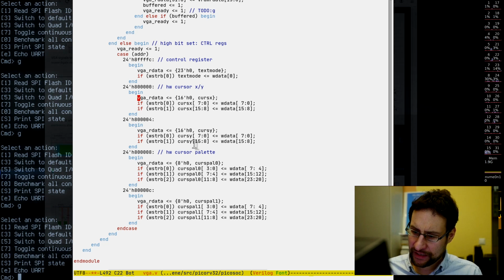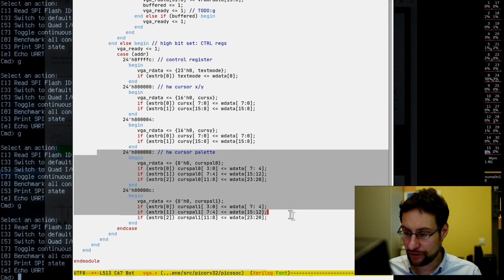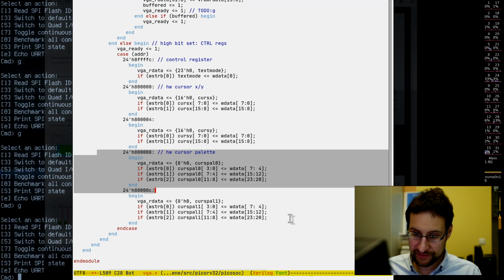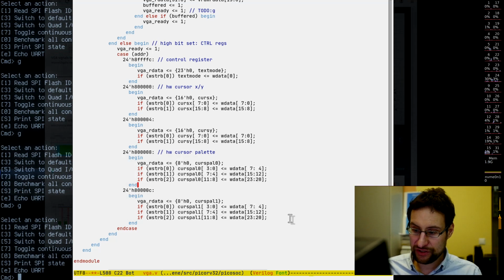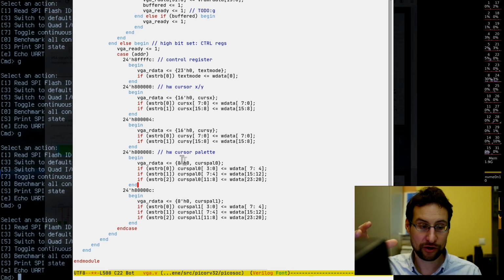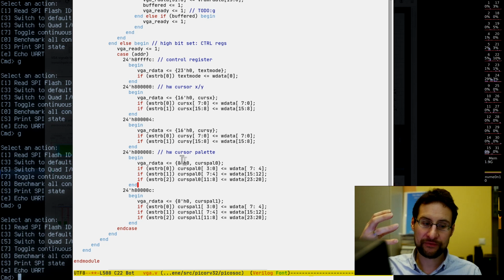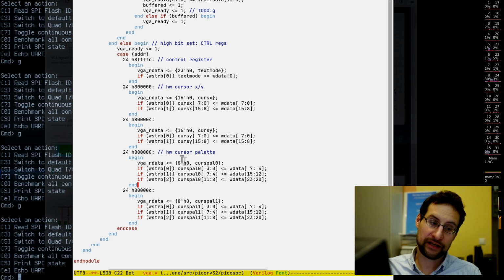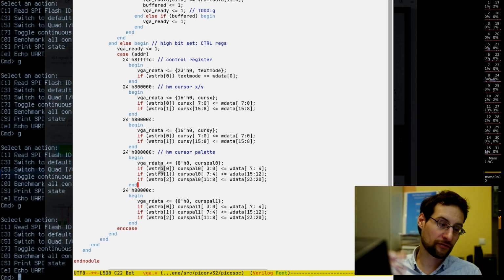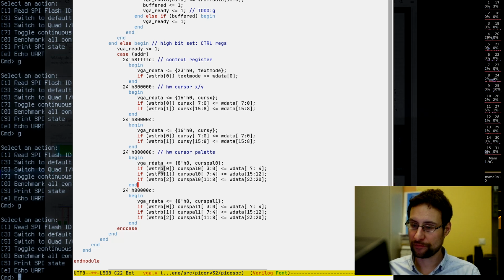mouse. And also right now I have not implemented the palette, so we would need to, as you see, we have here hardware cursor, palette of foreground and background. Theoretically, we need to copy this code or something similar, maybe more optimized, for updating the color output palette. So this again wastes a couple of way too many logic cells for just reading or writing or something of that sort. Theoretically, we probably want to do this.